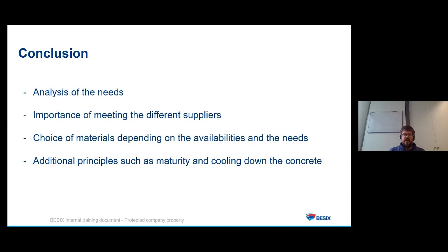Work on the mix design, and then if you don't have the choice because of availability, you can go for other principles like putting ice inside, or putting in pipes, or importing microsilica from somewhere else. But first, try to work on your mix design with the resources you have.